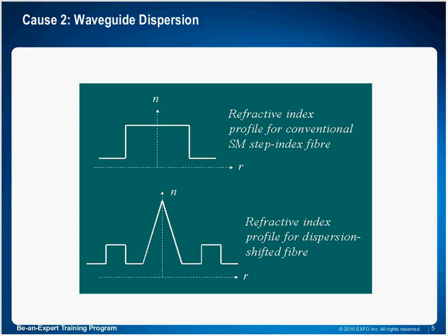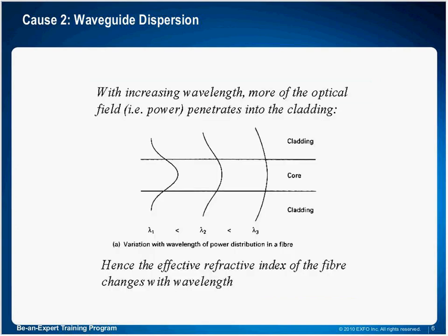And further out from this core graded index of refraction, we have two other levels of step index values. Now, what this is going to do is create conditions that change the way that chromatic dispersion occurs as the signal travels from point A to point B in the fiber, and it's going to dramatically decrease the amount of total chromatic dispersion that occurs in transmission. So let's see what this looks like when we put all of these different types of fibers together in a graph.